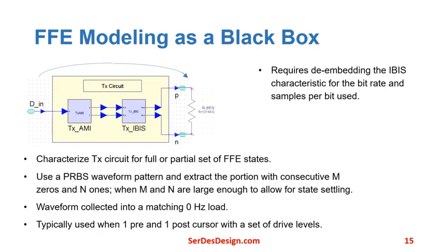The FFE modeling approach as a black box. For this modeling approach, the transmit circuit is characterized over a full or partial set of FFE states. The transmit circuit characterization process uses a PRBS waveform pattern that has a portion of the pattern with a consecutive set of M 0s and N 1s such that the M and N values are large enough to allow for state settling. The waveforms are collected into a matched 0 Hz load.